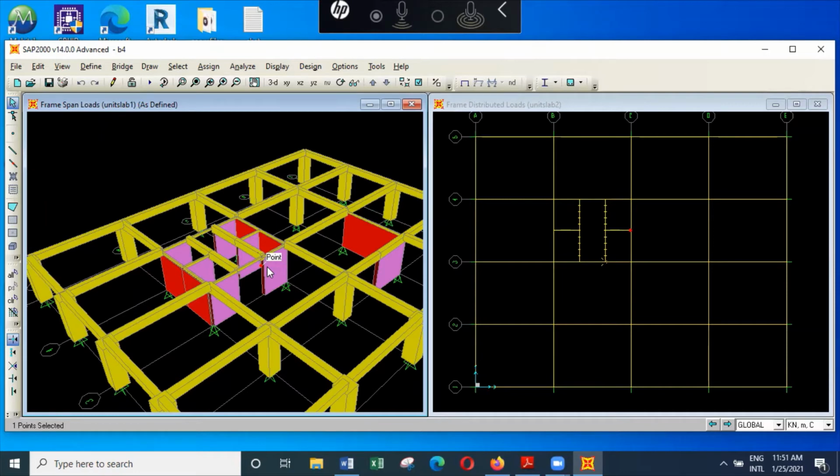2.1 meters means 7 foot, so you don't get that tall people. So that is enough, 2.1 meters. And generally, to do the fixing of the lift, we keep a height of about 2.2 or 2.25 meters so that all the additional panels of the lift can be fixed. So when you are entering the lift lobby, you can have an opening height of about 2.4 meters.